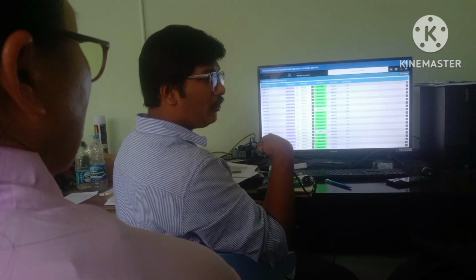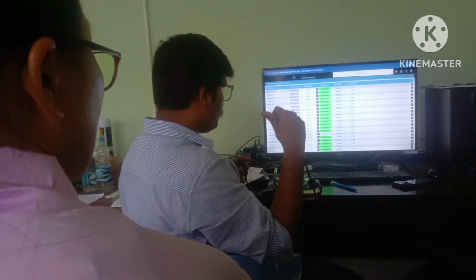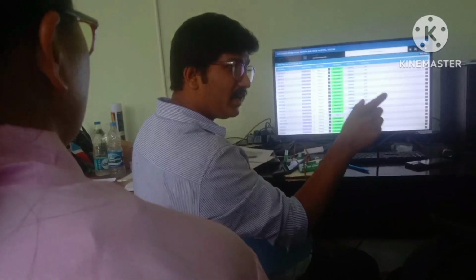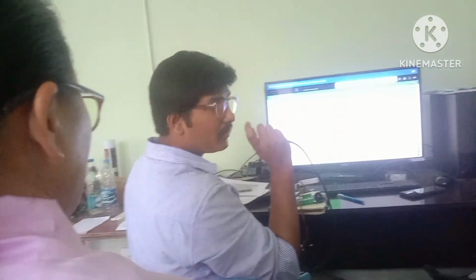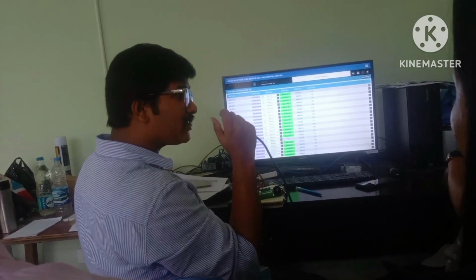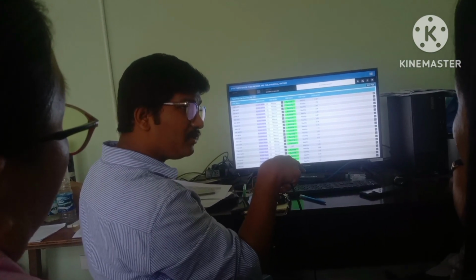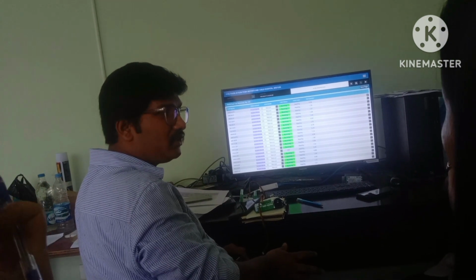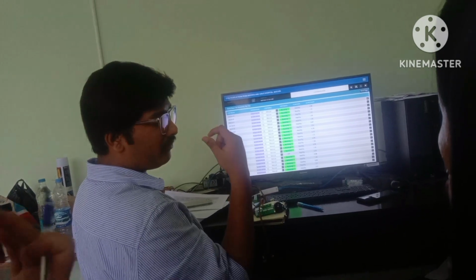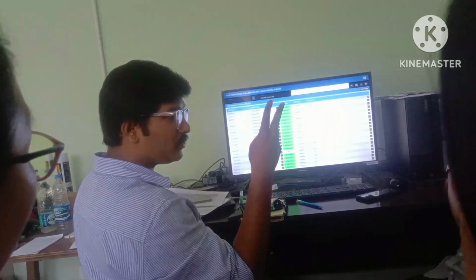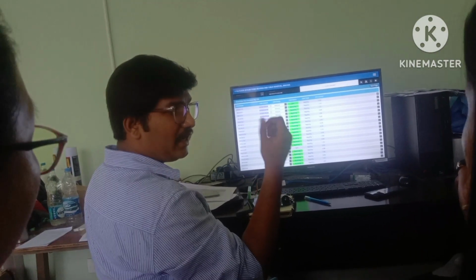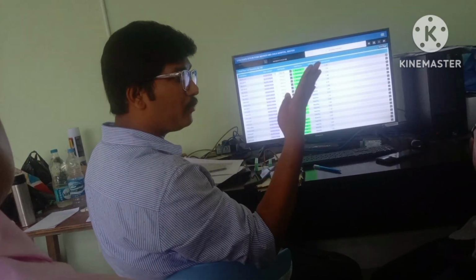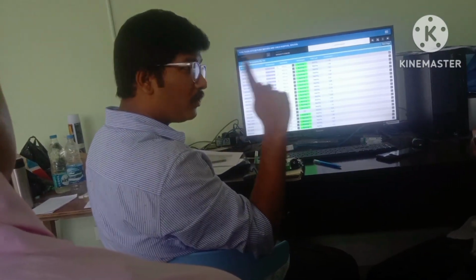So the perk of this is that we can configure everything in one card, in one packet of data. I have laid extra wires from the chiller to the CPM for hardwire communication. I laid that first because, as I told you, there are two types of IOs, digital and analog. In analog there are analog output and analog input. In digital there are digital output and digital input. And that is only for one device.